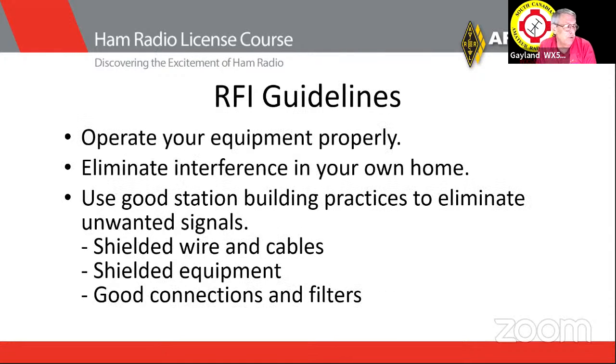Once again, operate your equipment properly. Good place to start with interference is at your own home. Make sure you're doing things that will reduce the noise in your own operation. And if you're reducing it in your home, you certainly are reducing it to your neighbors. Use shielded wire, shield your equipment, ground your equipment, use good connections and filters.